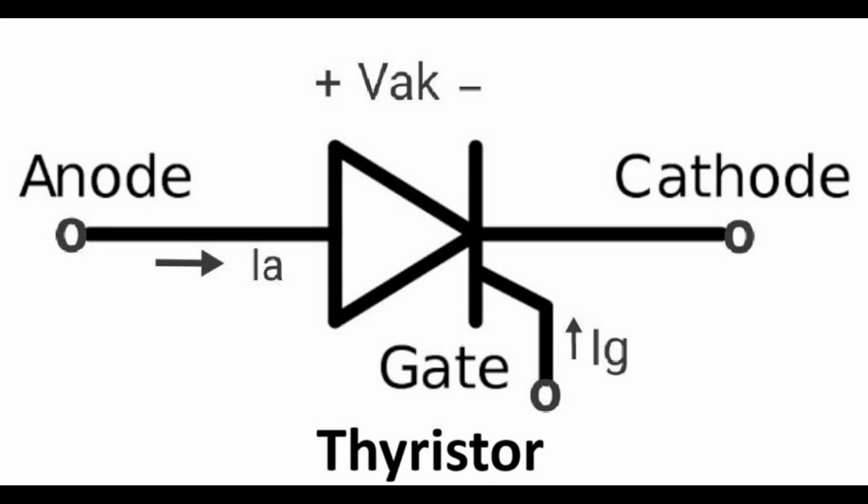Advantages. Symmetrical operation, provides consistent triggering in both directions of AC current, ensuring balanced operation. Simplicity, simple and reliable operation without the need for a gate signal. Cost-effective, provides an economical solution for triggering and protection applications. Limitations. Fixed breakover voltage. The breakover voltage is fixed and cannot be adjusted, which may limit its application in some circuits. Limited current capacity, not suitable for handling large currents, mainly used for triggering purposes.